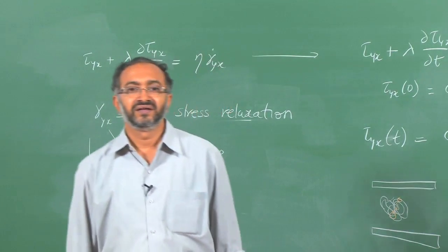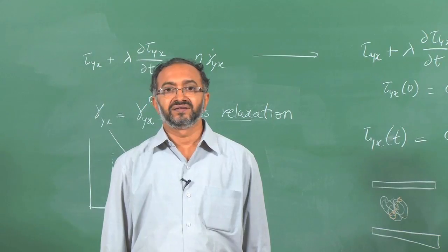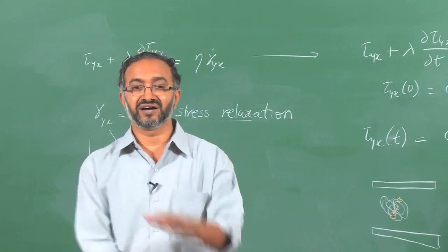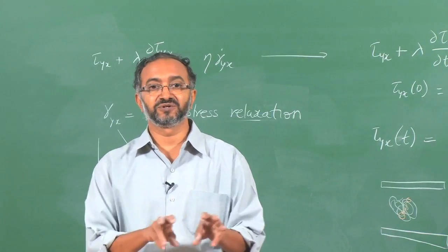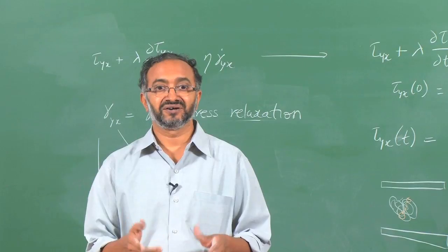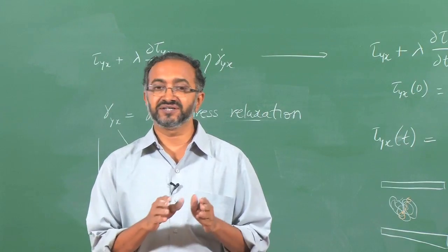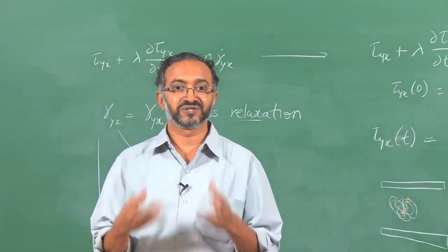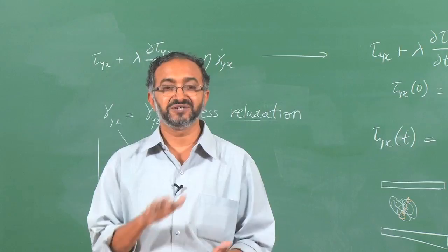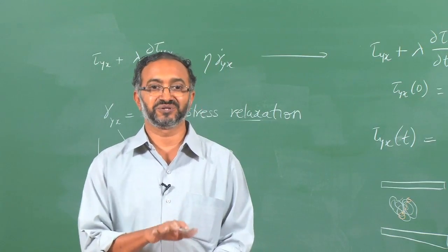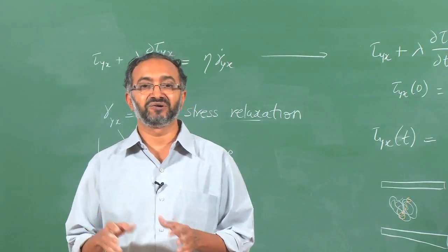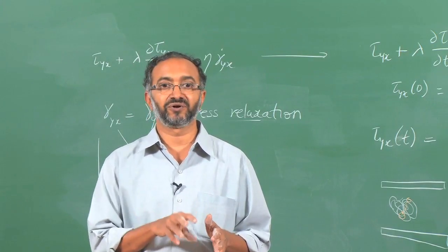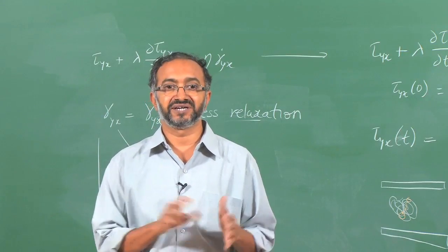But you told some fragments may fluctuate. No, fluctuation does not imply non-equilibrium, right. A jar of water with its random molecules fluctuating is not a non-equilibrium state. The fluctuations at molecular scale in fact are no indication of non-equilibrium nature. With those fluctuations the material is at equilibrium, only at molecular scale fluctuations are there. On the average, when you look, average velocity is not present, there is no temperature non-uniformity, there is no pressure non-uniformity and so on.